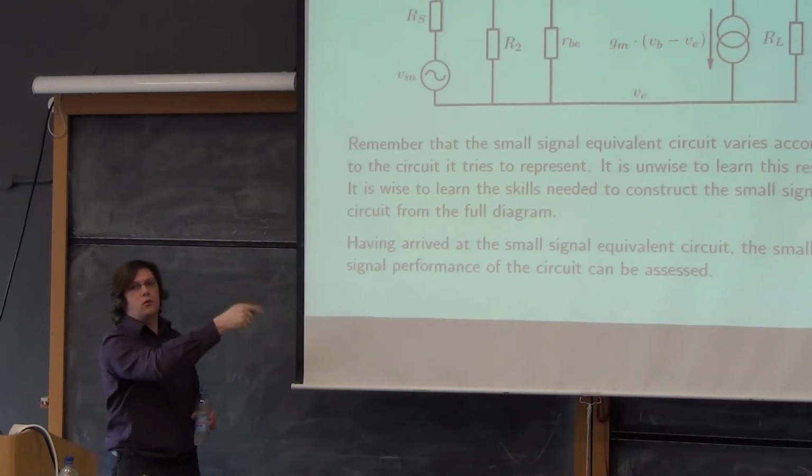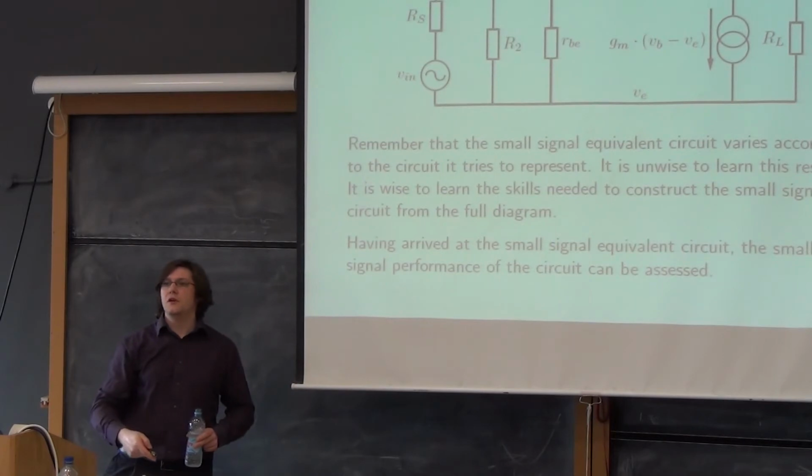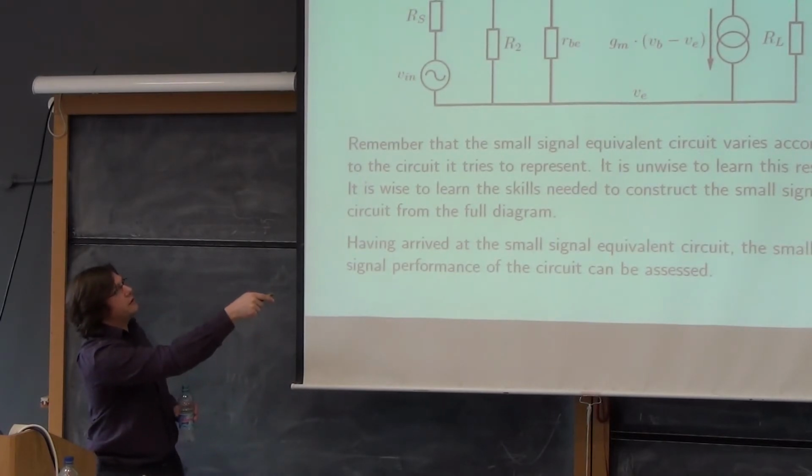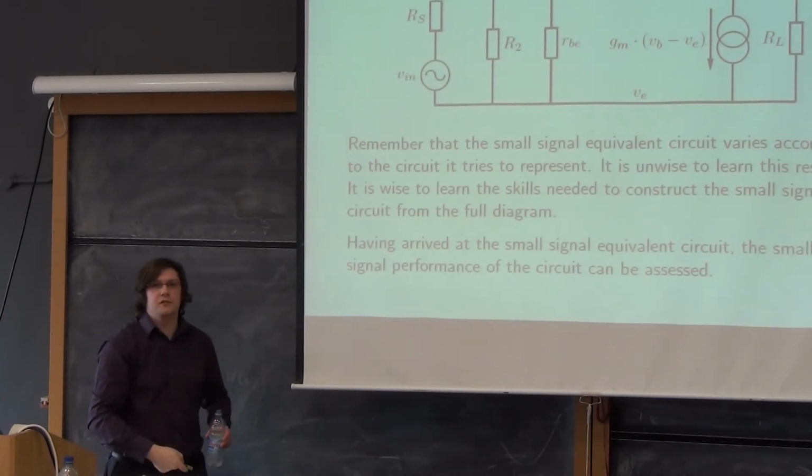So what we're doing is, all of these things are currents, because they're volts divided by ohms, which is amps. So what I'm doing is I'm working out the current that leaves down this pathway, I'm working out the current that leaves down that pathway, and then down that pathway. And then I'll have an equation for all the currents that come and go from this node, which is the first step of nodal analysis.